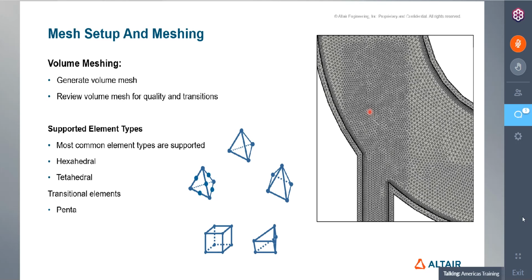The thing is, the smaller those elements are, the larger the number of elements, which means your computational time will go up. So that's one of the cases where computational power is a limitation. Technically you can generate very, very small elements, but always keep in mind that the biggest limitation is going to be the computational time, or how much computational power you really have.